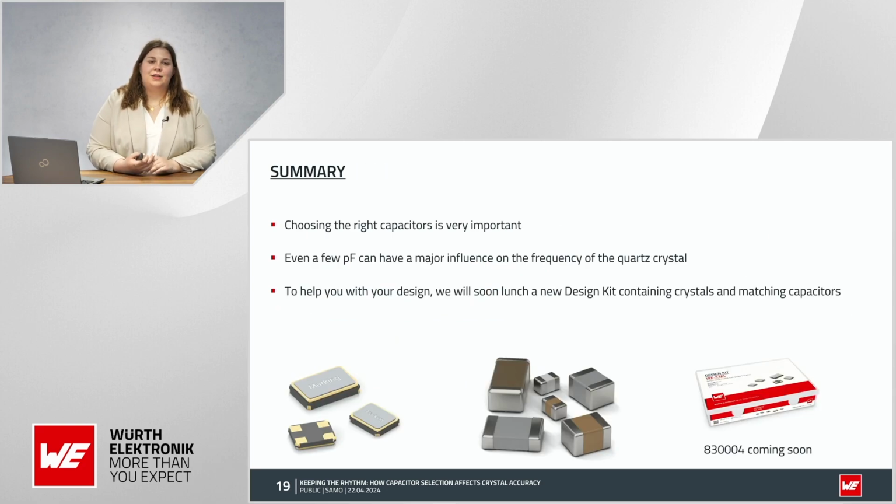So, a summary of what we learned today. We learned that choosing the right capacitor is very important, because even a few picofarads can have a major influence on the frequency of the crystal. We've seen that if you have a few picofarads less or more in your circuit, you could be out of tolerance. So you may have bought a really expensive crystal with a really good specification, but you ruined it by using the wrong capacitors. So really be careful here to make a proper design.